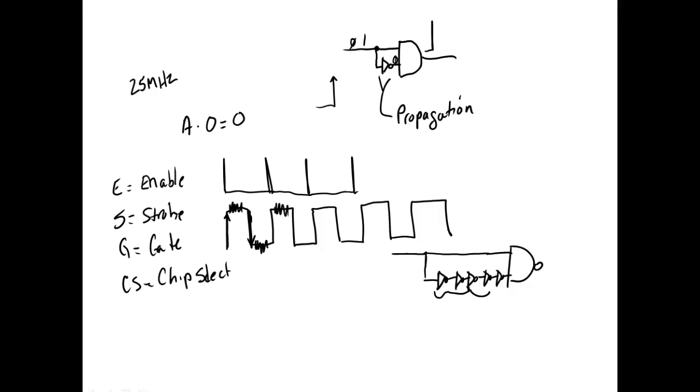They're either going to have a bubble indicating they're low active, or they're not going to have a bubble, which indicates they're high. If you see this, it indicates it's edge triggered. So edge trigger means it's looking for an edge. It's got an edge detect circuit in there looking for an edge. If I come over here and see this, then it's looking for the rising edge. Right? You understand? If I put a bubble on it, then it's looking for a falling edge.